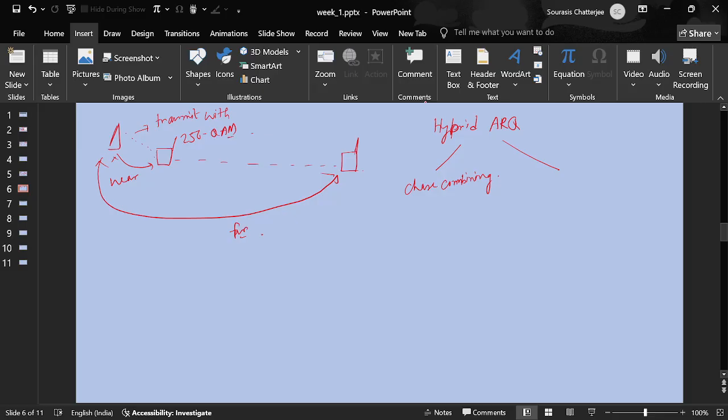If this is implemented, consider this scenario: the user moves to a far away region, and the base station transmits 256 QAM. The user fails to decode because its SNR is now much lower, so it sends a negative acknowledgement. Now at this particular instant, what is the base station going to transmit? Is it going to transmit the same packet again? Okay, retransmission. Transmit the same data.